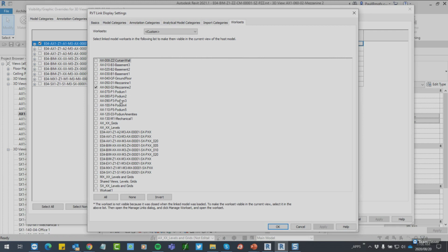So if we did this in the way that we did with the smaller file, then for the structural and the architectural, and the mechanical, possibly not the mechanical, but definitely the structural and the architectural, we could isolate per level the geometric elements so that we can clash that, say, with the piping in the mechanical level.